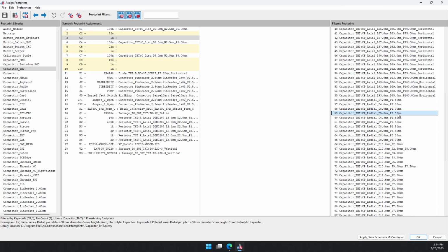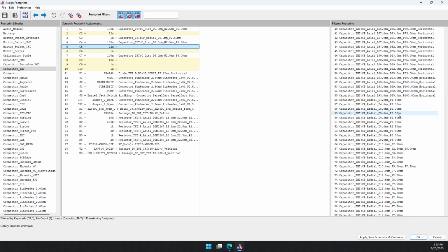Okay, let me measure the legs one last time and see what exactly we are getting. Are we getting a 2 or a 2.5? Starting to look more like a 2. The pattern looks more like a 2. But I stick with my reasoning. I'll go with a 2.5. So 1U, 5 mm, 2.5. And now let's find the 10U and the 22U.